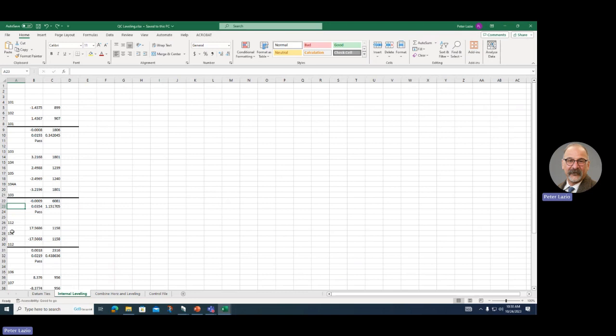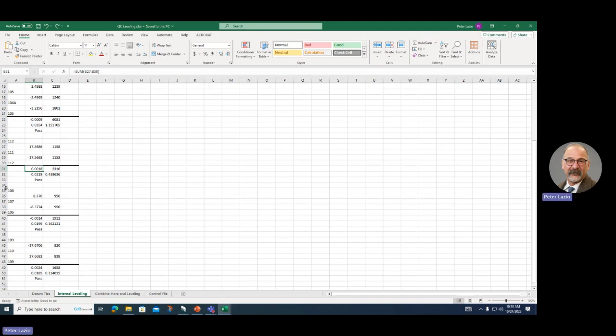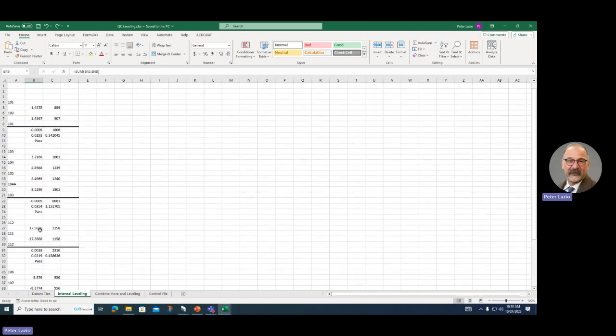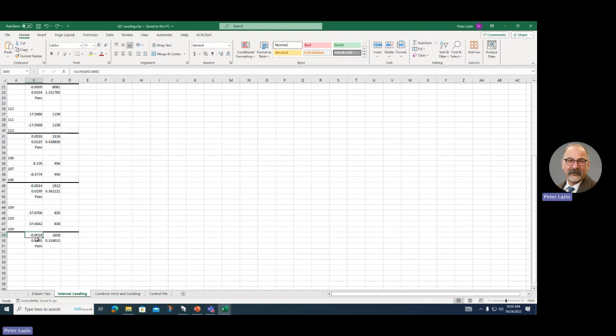Here you had 111 to 112, you had 18 thousandths, 106, 107, 14 thousandths, 24 thousandths. That's the high one. And we discussed it, you guys are using your turtles and your turning pins and everything, and with a digital level, this is what you should expect, especially if you're balancing your foresights exactly. But just keep these numbers in mind.